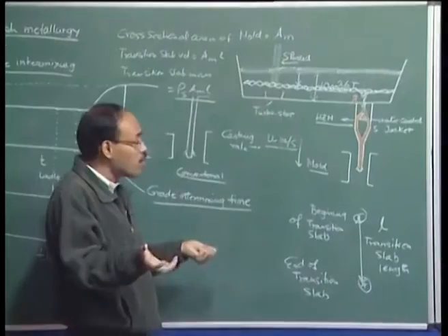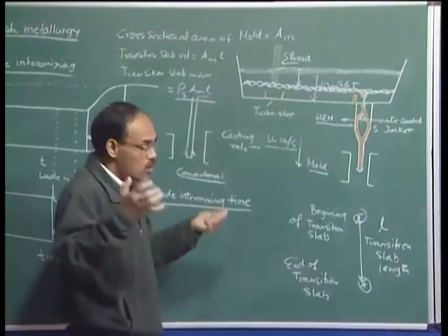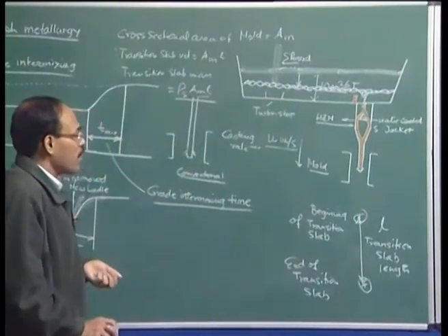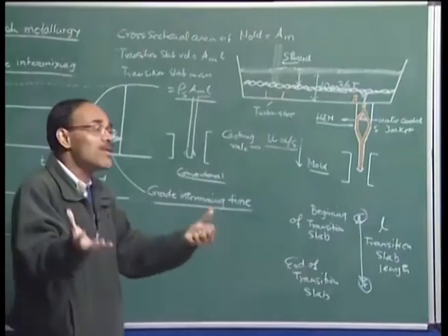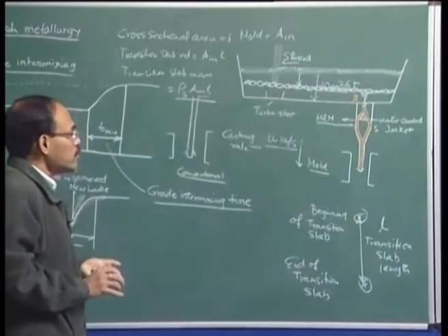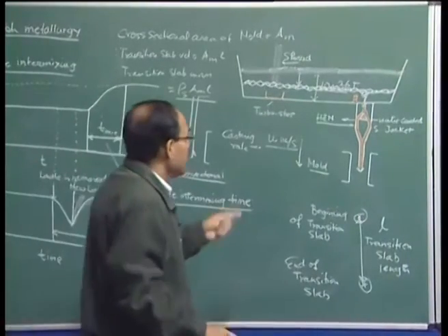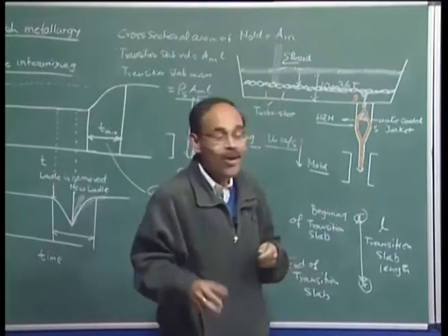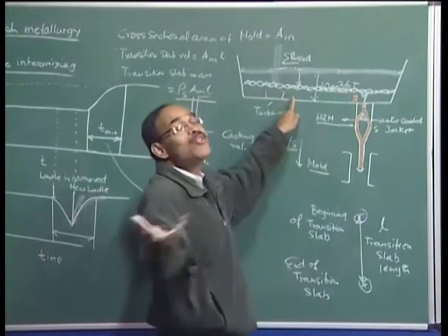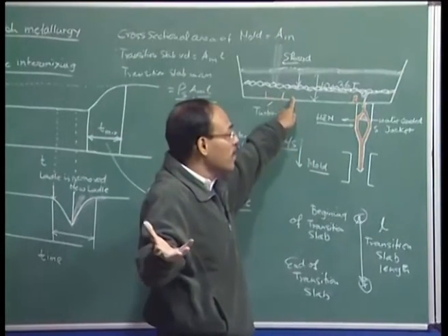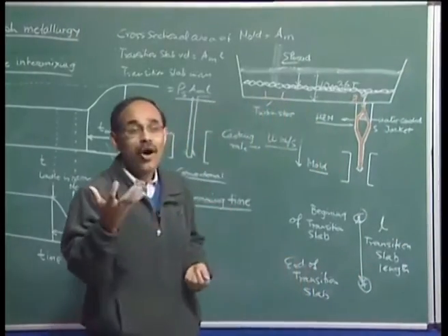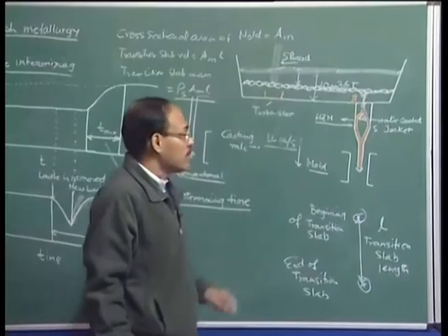So, the tundish is now broken, okay, and the refractory is to be relined. The skull is going to be salvaged by physically breaking apart the refractory lining of the tundish, and the skull is then taken and recharged back into the electric arc furnace. Every plant very meticulously weighs that skull, because they want to find out what the yield from the tundish is. So much material they have charged into the tundish, and how much billet or bloom they have formed, okay, and the amount of tundish skull really gives the plant an idea of the yield in the continuous casting tundish system itself.